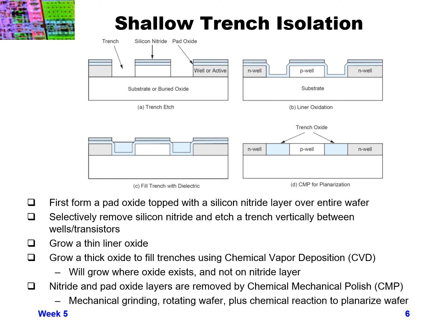The next step is we want to perform an oxidation. We grow a thin layer of liner oxide in only the areas where we have exposed silicon. We can grow that through a dry gate oxide type growth, and the oxide won't grow on silicon nitride because the oxidation will only react with pure silicon, but not with silicon nitride.